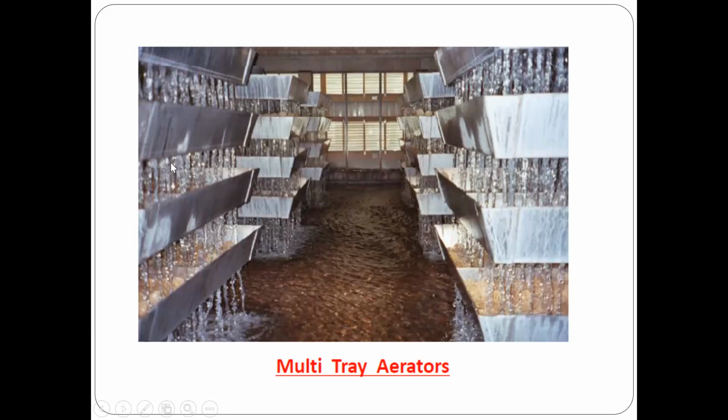So what is the process? We have to feed the raw water. From the top it will get percolated, or it will trickle down. So this water trickles down through the trays. These trays are perforated. Sorry, I forgot to tell you, these are the perforated trays.